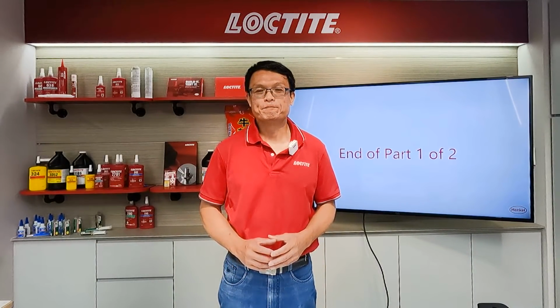We chose the pendulum to give an impact energy to the specimen. We developed the specimen according to industrial practice. That is the composite material, and we also did the surface preparation with sandblasting, exactly following industrial practice. We also chose 5 epoxies covering most of the candidates used by the industry, trying to understand every different feature of the epoxy that can contribute to the final impact strength of the material we are going to bond. This comes to the end of this part.